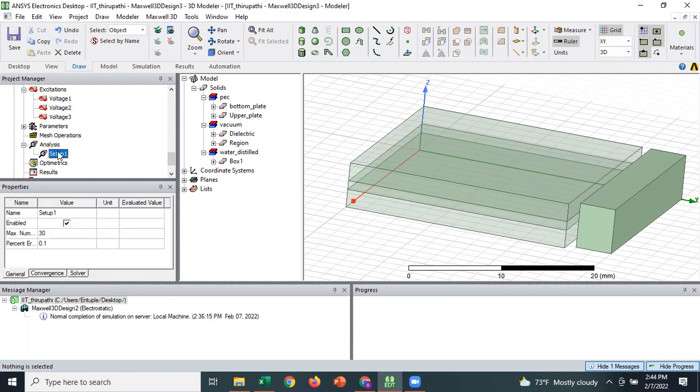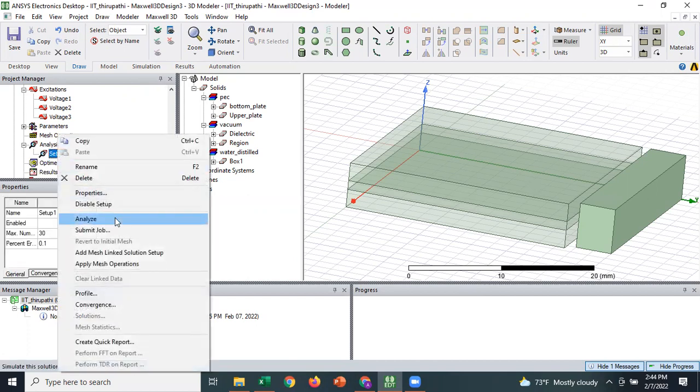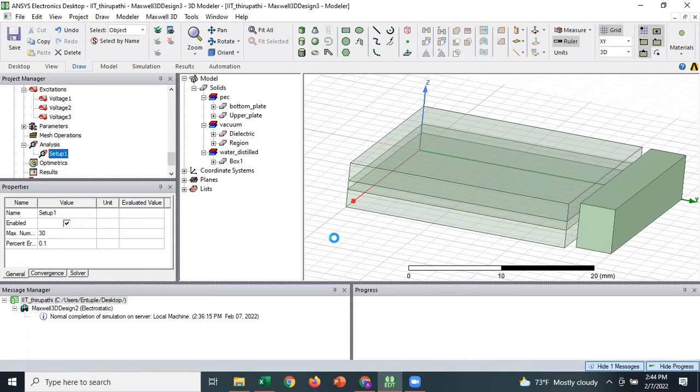It is also going to take a little bit more time for that. Since I'm having a memory issue, I don't know if it gets complete. But maybe you can increase or decrease the accuracy to 0.5%. I think around 0.2% you could solve it. For the time being, shall I change it to 1%? Yeah, 1% you can change, no problem.